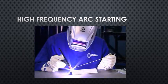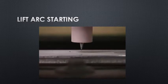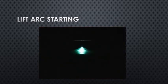All right, high frequency arc starting application. If you look at this image, which again will be a video in the online presentation, you can see how close the tungsten electrode is to the work and where the operator is basically going to engage the foot pedal, start the high frequency, it'll jump that gap, the arc will follow, and he can begin to add filler metal to the molten puddle as he travels on the screen from left to right, pushing the puddle in the direction of travel.